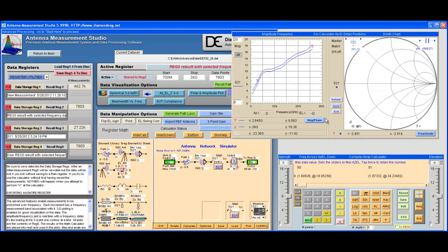And it should be mentioned that using the mirror reflection method requires a wide band of measurement with a lot of frequencies. Because of that, it's not possible to measure narrowband antennas due to the fact that too much of the signal content never really reaches the antenna.